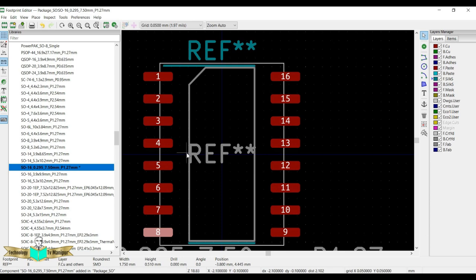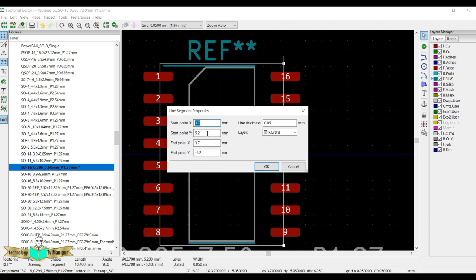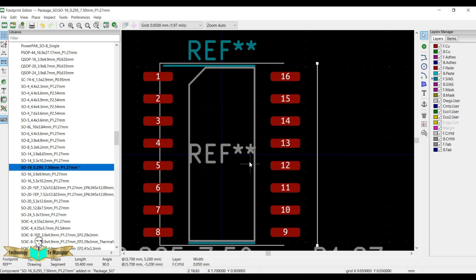With this we completed the other side also. Now I need to change the location of this one. So let me just type the part. You can double click on this, but we added around 3.8, so I will add only 3.8 to this X location. And here also I'll make it 5.7, must be perfect.